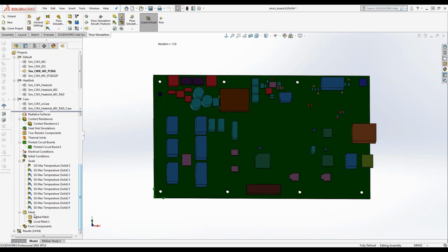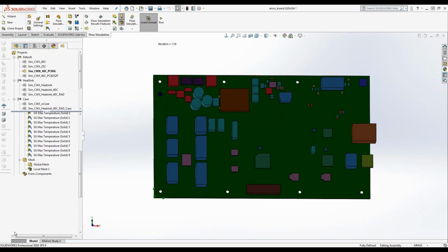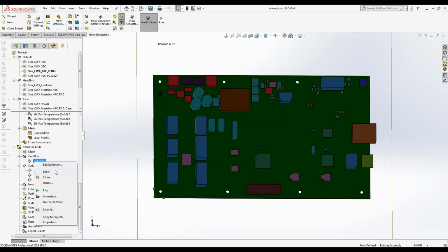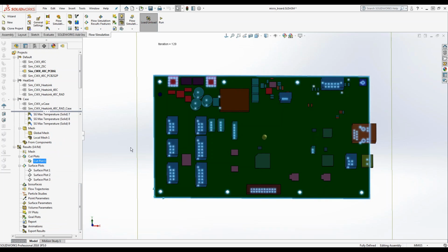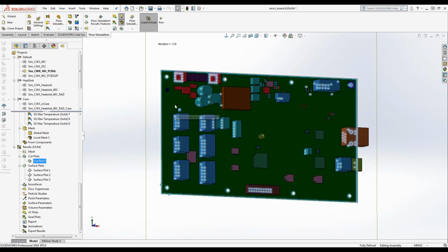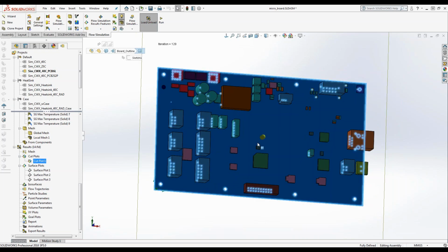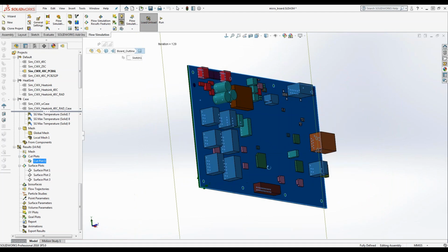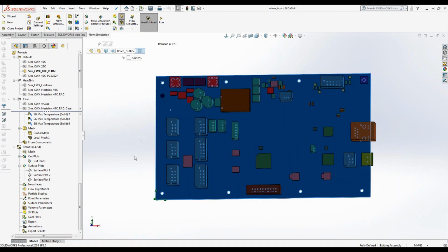Another thing that you would want to set up is if you have some high detail areas, we call that meshing. So in this design here, I've set up global mesh and local mesh. That allows me to set up a fine grid in areas that need more detail. And when I'm done, I can see, for example, if I'm looking at, let's see if I can make that show better for your screen. I don't think you have the resolution to see that, unfortunately, in this presentation mode.